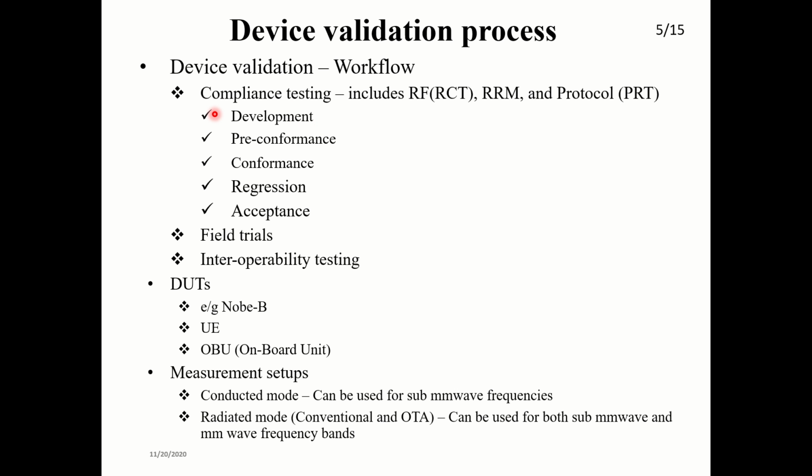For example, if your antenna is there, you will go and check it. In the earlier days, if you wanted to capture the radiation pattern, they would rotate the antenna. Some students might have done this, or if you have graduated already, you might have done it in the microwave lab. You rotate the horn antenna, note the reading, rotate the horn antenna, note the reading. Finally, you plot those points in a graph, a polar plot, and then you see the radiation pattern.